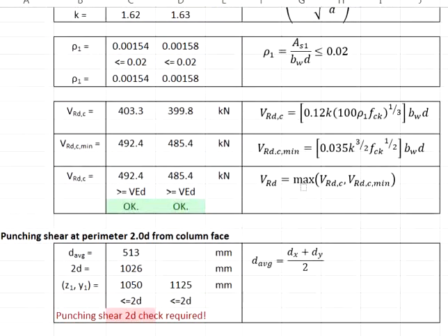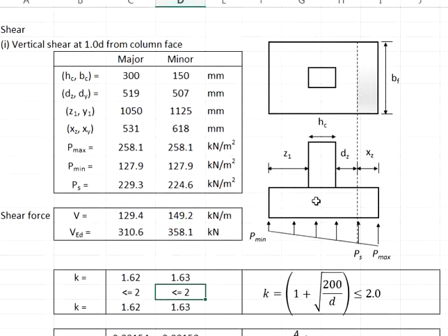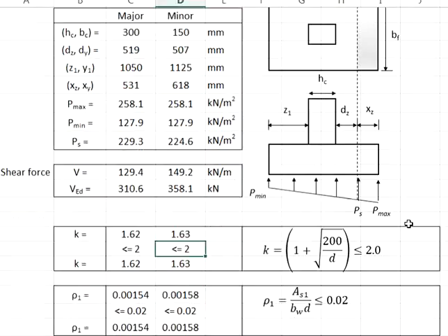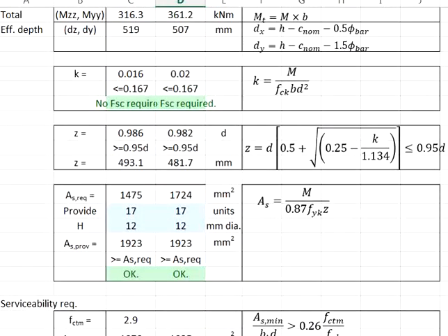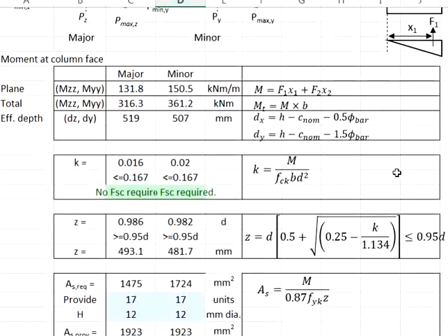As a result, this will slightly increase the resistance in the minor axis, but slightly reduce the resistance in the major axis. Those are the influences of the arrangement of the reinforcement. You can follow this arrangement. As you can see from the result, there are not really significant differences. You can also choose to make it more optimized by swapping the arrangement of the reinforcement.